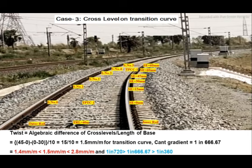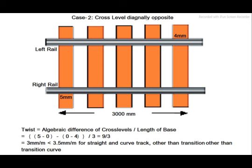On a transition curve, therefore, the twist introduced has to be kept well within limits. The cant gradient shall be limited to 1 in 720 or 1.4 mm per meter on Indian Railways. However, in exceptional circumstances, the cant gradient may be relaxed to 1 in 360 or 2.8 mm per meter.